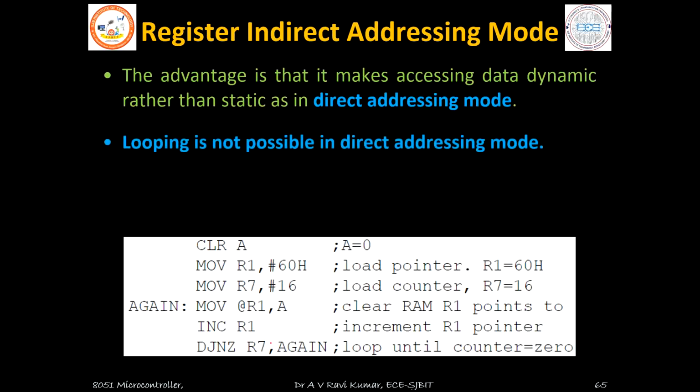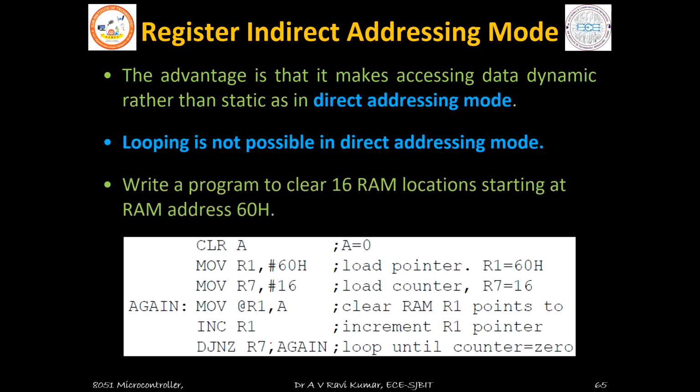So the second main advantage is that looping is not possible in direct addressing mode, while looping is possible in indirect addressing mode. So let me write a looping program. Here I want to clear 16 RAM locations.